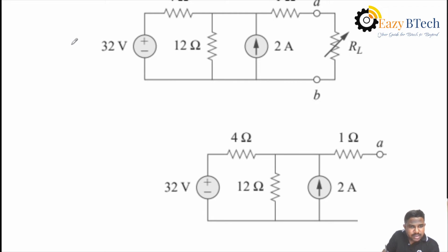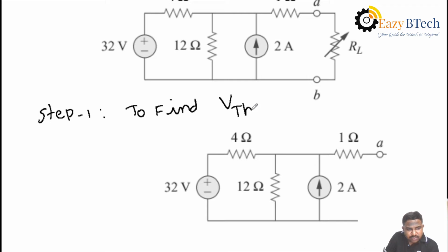That is step 1. In solving Thevenin's theorem, step 1 is to find Thevenin's voltage, denoted by VTH. That is the first step.